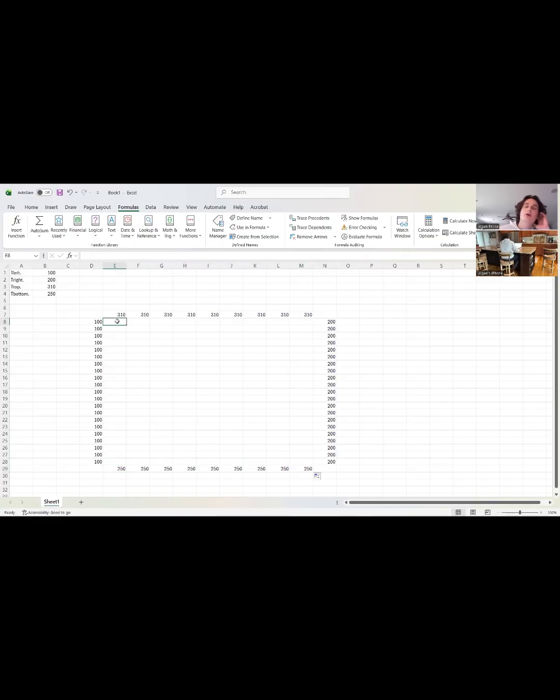And so when we look at our equation, right, we had from before, T i j equals T i plus 1 j plus T i minus 1 j plus T i j plus 1 plus T i j minus 1 all over 4. So how are we going to do that in Excel, right? So we determined that it was just the average of what's around it, right?